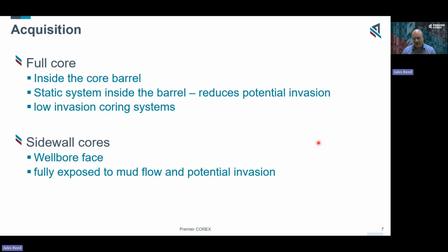There's also, depending on the mud balance, whether you're significantly overbalanced or you're close to balanced in the coring process, that's also going to have a bearing on the properties of the sidewall cores potentially. So if you have significant overbalance while you're acquiring the sample during the drilling, then there's the potential for fracturing or higher invasion.